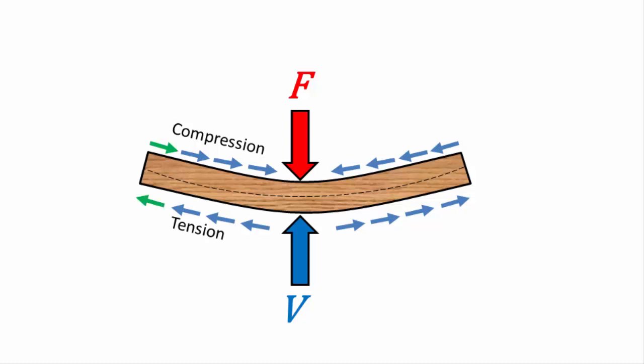If we look at the horizontal forces at the left end of the beam, the normal convention for beam analysis is that we start at the left end. We see that the top of the beam experiences compression forces to the right and the bottom end of the beam experiences tension forces to the left. The two shear forces act to rotate the left end of the beam in a clockwise direction. This clockwise direction is taken to be positive in the normal sign convention for beam analysis.